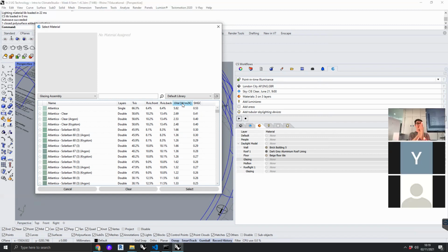What the U value tells you is how much of that energy is going to get transmitted from one side to the other. So a really low U value, rather than thinking about it as good or bad, means more heat energy is going to stay where it's supposed to be, or where it was. Depending on which climate you're in, you may or may not want that. Does that make sense? And this is why the site analysis is really important, because if you want the same temperature inside as outside, you want a high U value. You want things to be able to pass through easily.